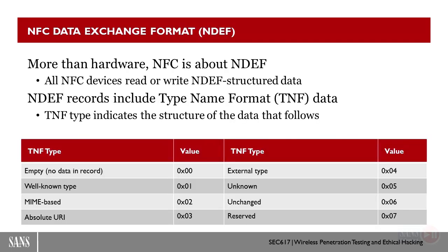The big one here with NFC is that it is not so much about the type of hardware and the role change for the PICC and the PCD. And the multiple reads, that's typically a function of the hardware. NFC is all about the way we're choosing to exchange the data in a structured format with NDEF. So the data that we're exchanging with those reads, the potential multiple reads and the exchanges, is all NDEF formatted data, in that we have a standard for exchanging that data.